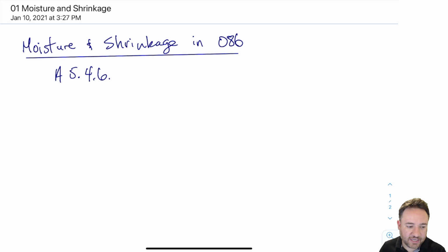So you can refer to that in your wood standard printed copy. In this, it talks about how we need to pay attention to shrinkage, and it gives some reasons why we should take into account shrinkage, including non-uniform movements, metal components that are supporting large timber components, which was a qualitative example I gave in a previous video about moisture content, and also trying to account for differential movements.